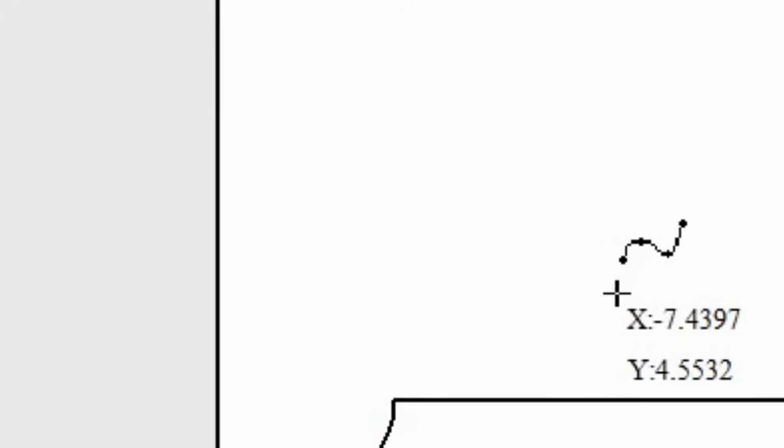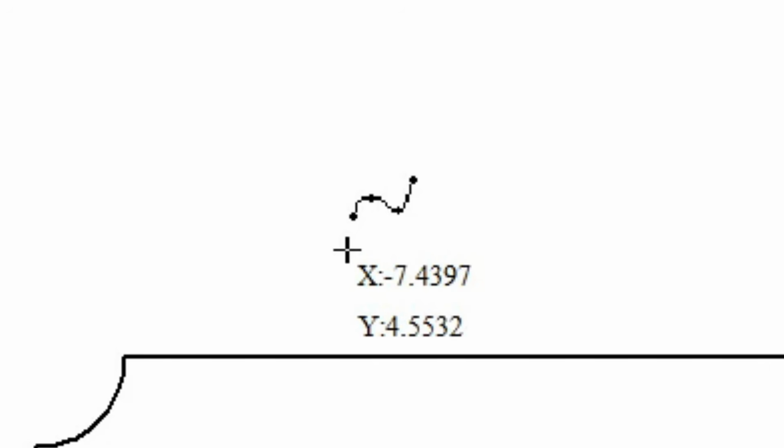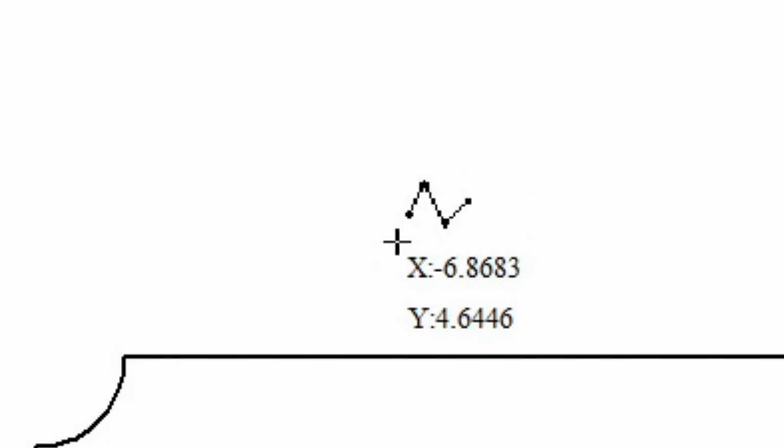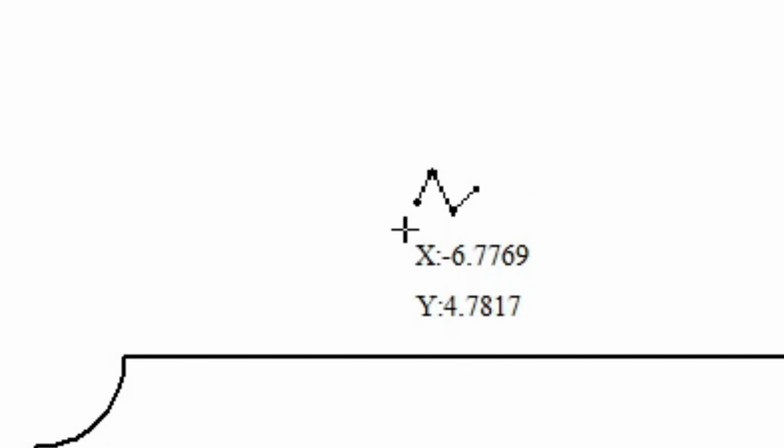Select that. Now there's something I want you to notice about this polyline right now. You see the little indicator above my cursor. It is actually not a straight line. It's kind of a swirl line or an S line. That is telling me that we are currently in the draw curve mode within the line function. So what you need to do is press the letter S if you see it like that, and that should change to a straight line just like that.